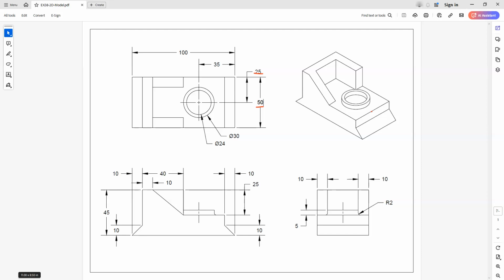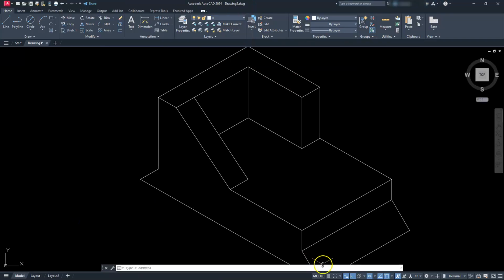So that tells me by default at this midpoint, I can create a line. Now I just need to know how far to go back to define the center of my circle here. Remember that I have to subtract off whatever the distance is between here and here from this number. Well, it gives me the distance here at the bottom, which is 10. So this line going back here has to be 25, right? So all I'm doing is just going to draw a line from this midpoint going straight back at 25.